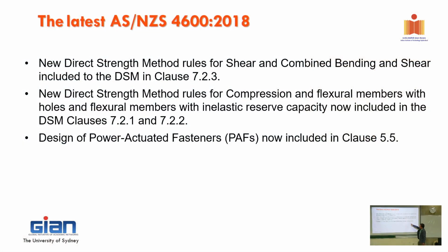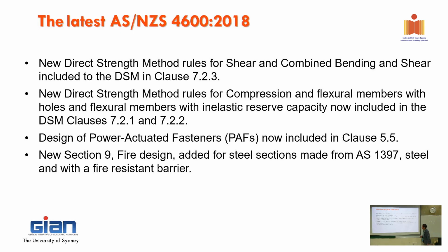So in order to design that, of course, you need rules. So in the latest AS/NZS 4600 2018, we introduced the rules for that. So you can actually design those types of fasteners in AS/NZS 4600. Right, and then importantly, we are also including the design for fire. So fire engineering now, you have equations to design for fire. I think it's the first time in a cold-formed steel design standard.